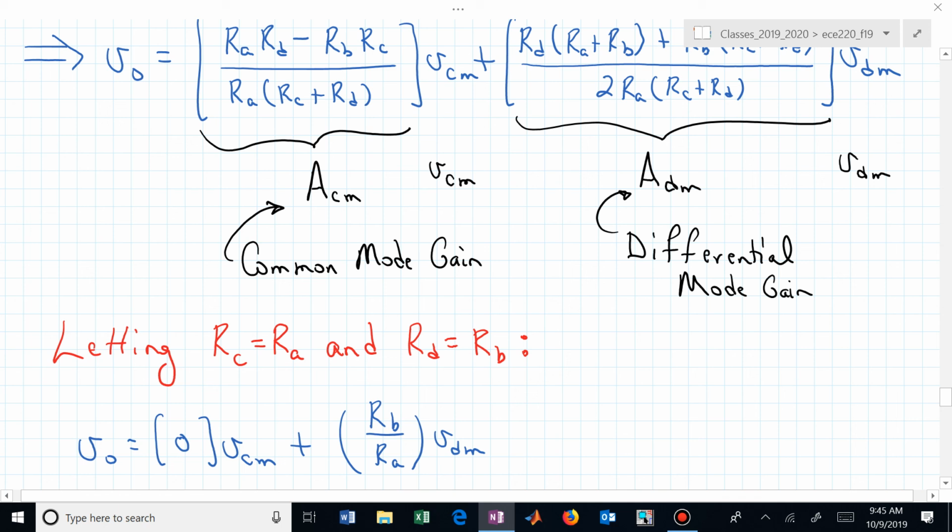What have we done to the noise? We've annihilated it. We've zeroed it out. We've forced it to zero by subtracting V sub A and V sub B, both containing identical noise, but we've preserved this difference mode, and we've amplified it. Now the output is only a function of the difference between V sub B and V sub A, and that's what's holding the information.